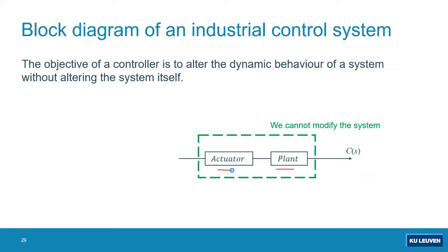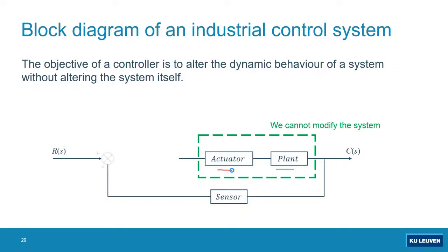Because we cannot change anything in our DC motor as well as in our power supply, what we can do, we close loop it. We measure the output, the rotational speed of your DC motor, using a sensor, we close loop it, and then we put a desired designed controller in order to make your system respond as what you expected.